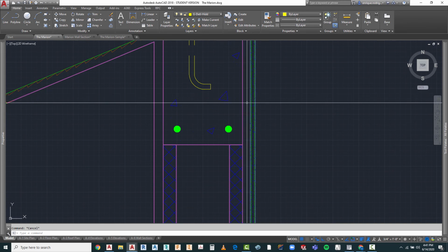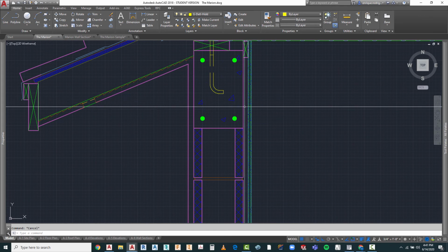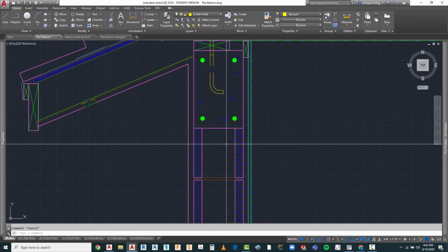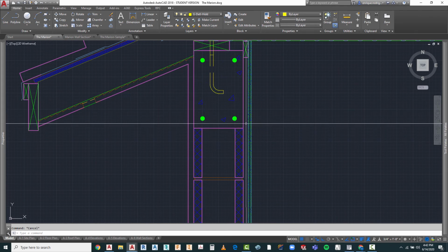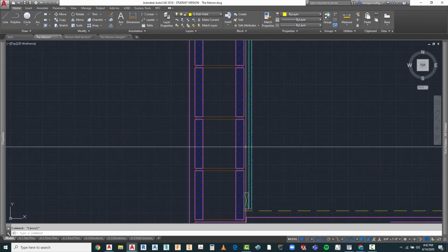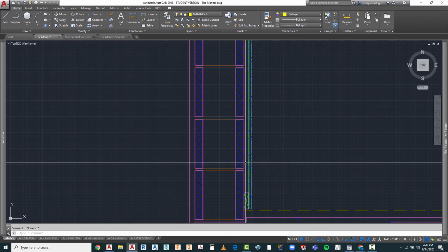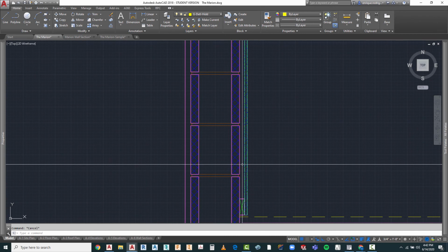It's about a 4.2 R value, and what that does is allow for additional insulation for the walls. So it really isn't a blank space. What this space also does is allow for the electrical boxes, conduit if you have any, or your Romex to go through there to help you get some of the electrical wiring, the boxes, the outlets, etc. that are going to go there.